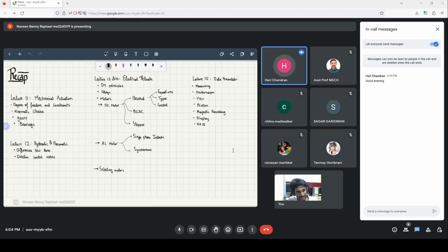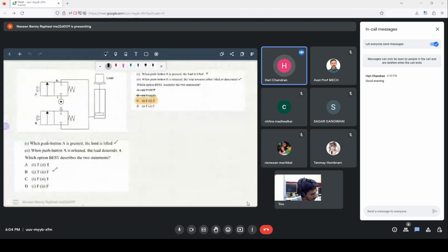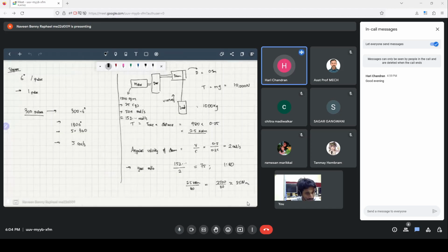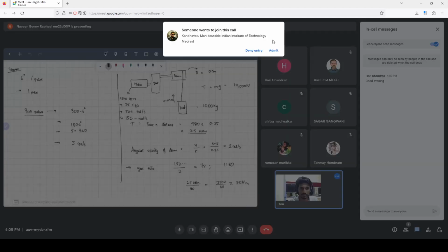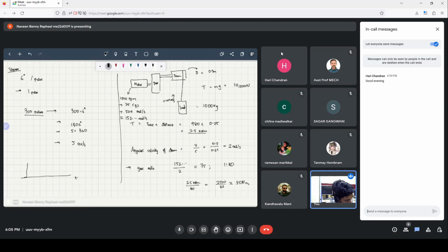Technically, it doesn't directly sense the speed of the motor, but if we know the exact position and how fast it changes, we can get the speed. Say we are getting the output from the Hall effect sensor over time, and we get like 4 pulses.